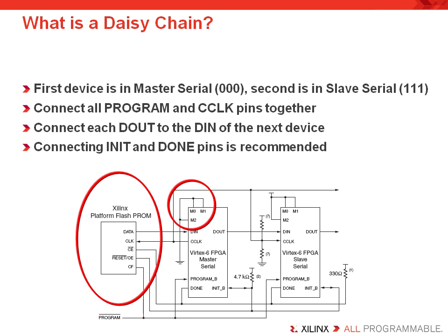We also have connected the INIT pins together. Tying the INIT pins together allows for error checking the entire system. If one is clearing, the node is pulled low and configuration of the system is not allowed to continue until all the FPGAs have been cleared. Then the node can be pulled high by the resistor. Likewise, later when the FPGA is loading its bitstream, INIT can go low on any one of the FPGAs, indicating that the bitstream has failed its CRC check and the configuration is being aborted.